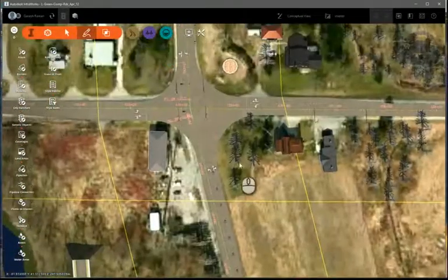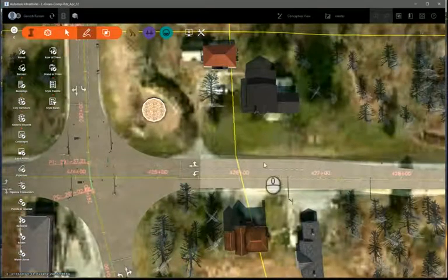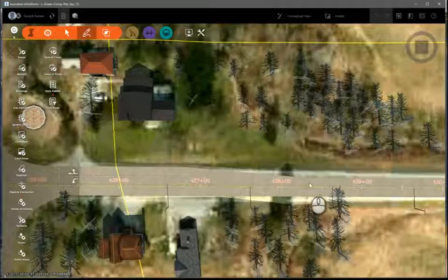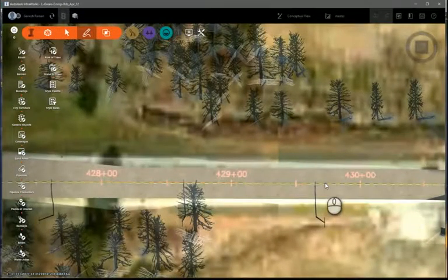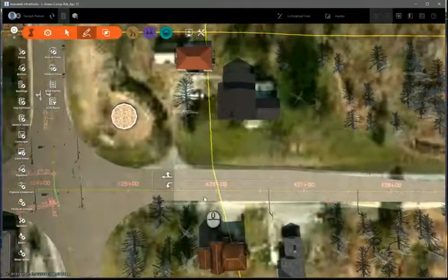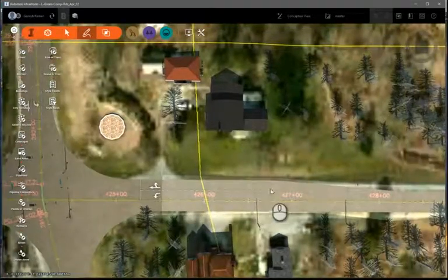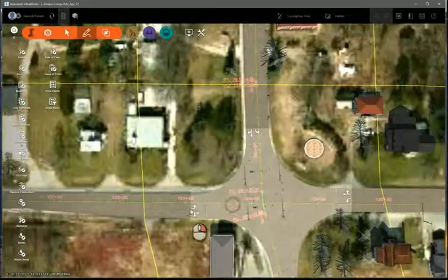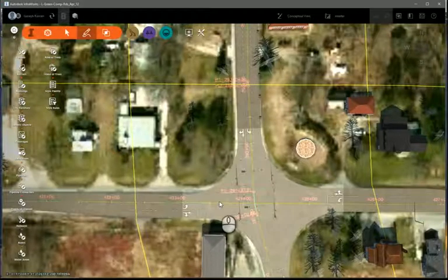The problem in this case is because the right turn lane was added as a transition in the component roads of InfraWorks to create an extra lane from the original 2-lane to create a 3-lane overall at this junction. So what this does is that it adds lanes to the right side, and it adds lanes on the right side in the opposing direction, which creates a mismatch for the through lanes at the intersection.